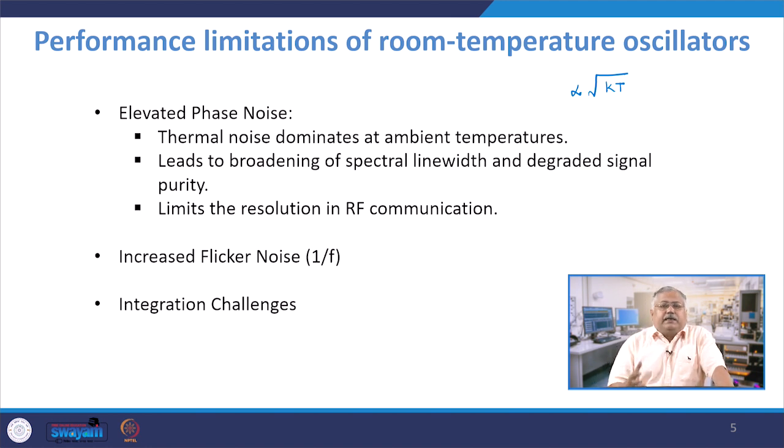Finally, you need to integrate this oscillator with the system, right? And that is the challenge, because the oscillator output has to be matched exactly, the impedance has to be exactly matched with the load, so that the power is transferred very easily from the oscillator to the external source, especially the pulse. Moreover, oscillators, as I discussed with you, are primarily responsible for generating clocks, but the problem is these clocks will be routed through long interconnects across the network where the chip is. When this happens, you will also have major challenges related to jitter and noise.